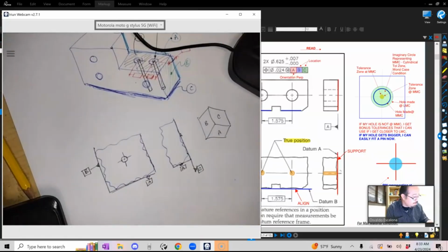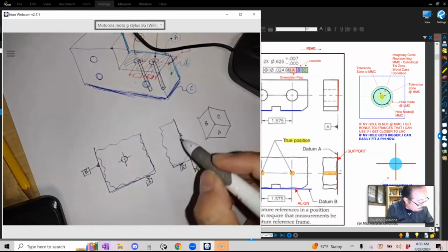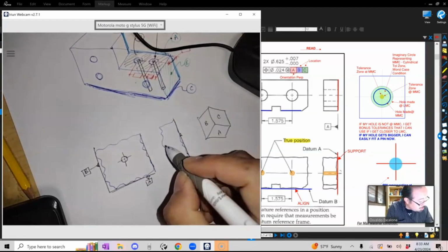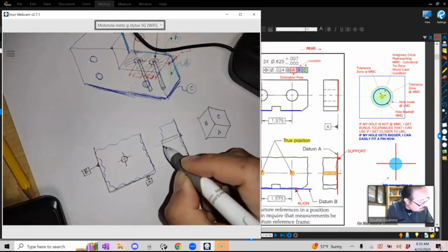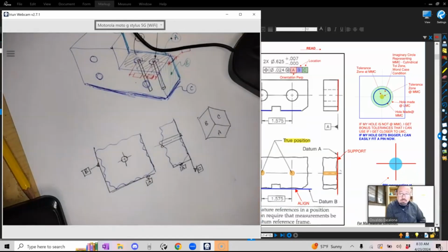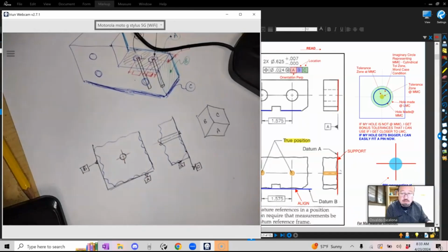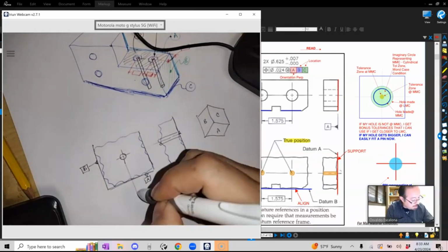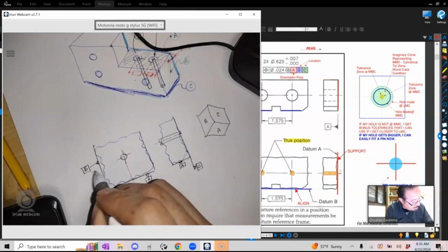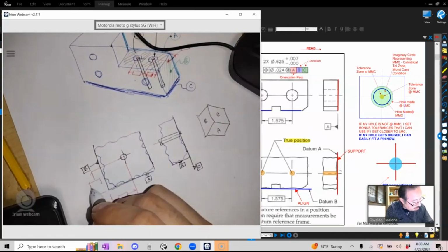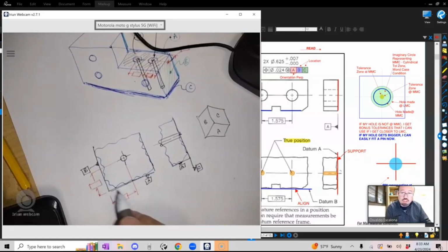And let's say my bullseye, remember that my bullseye is perfectly located based on perfect conditions. So let's say my bullseye is going to be somewhere there, and the tolerance zone of the cylinder will be somewhere there, okay? If I have this bullseye and I want to position it, I gotta give it basic dimensions, right? Another basic dimension there. Basic dimension, right? True position.